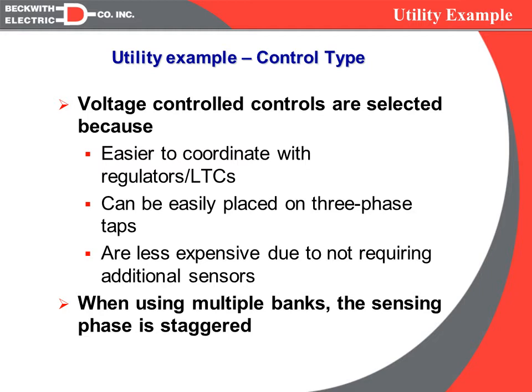And you cannot do that with a VAR control, because then your VAR control would only be monitoring the current and the VAR flow on that tap instead of over the primary main circuit. So with voltage controls, we can place them anywhere we want.